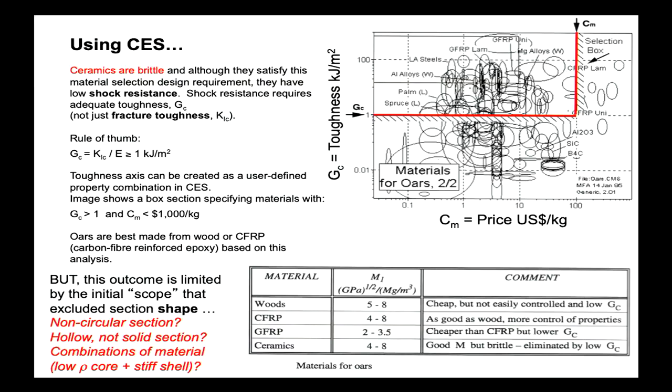The limiting line, the limiting point, is going to be difficult to know because after all, if you haven't got a feel for what toughness is and what range of toughness is, that's problematic, which means back to resources, back to experts of some form or other to get a number for this GC notion. And GC corresponds to fracture toughness divided by Young's modulus, by the way.